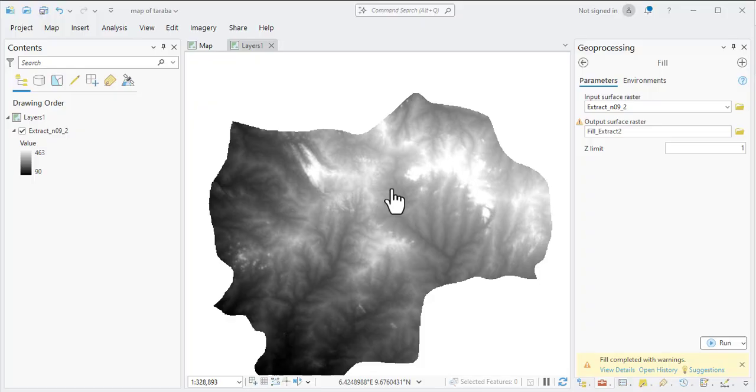But before we proceed, I'd like us to look at what really makes someone create a slope in percent or in degrees. The major difference is, I think, simple. In one sentence, when you're using degree, it's going to be used majorly for terrain analysis, while when you're using percent, it's basically used for engineering. Knowing this little difference will solve a whole lot of issues.